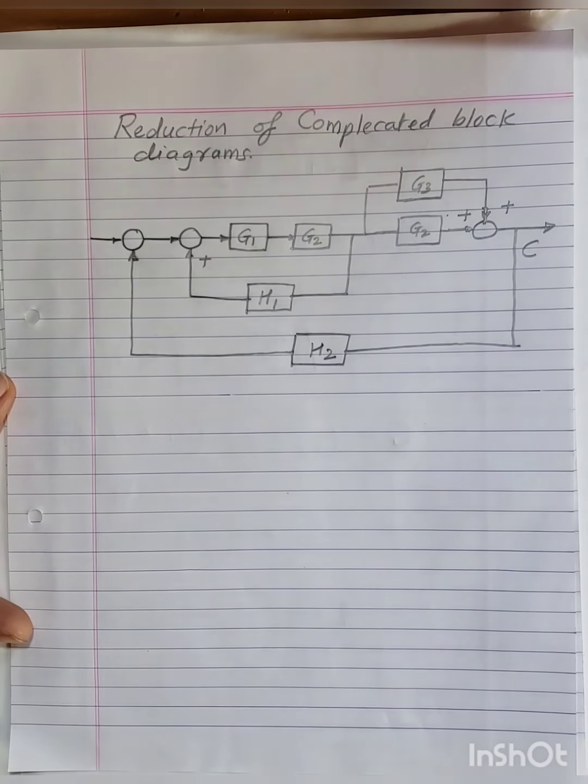The technique developed in the preceding paragraph provides the necessary tools. The following general steps may be used as a basic approach in the reduction of complicated block diagrams. Each step refers to a specific transformation listed above. Step 1. Combine all cascade blocks using transformation 1. Step 2. Combine all parallel blocks using transformation 2.